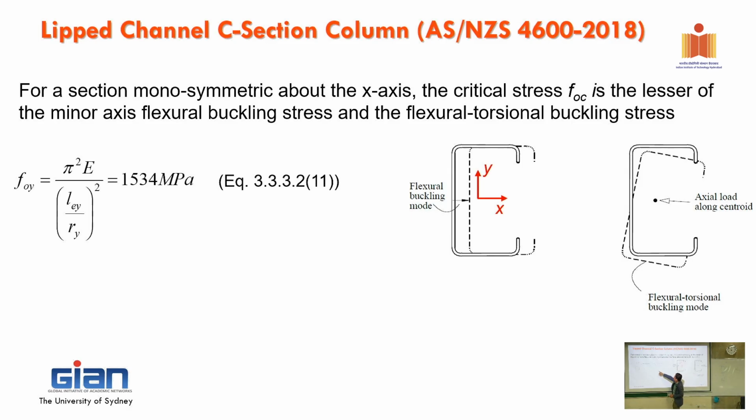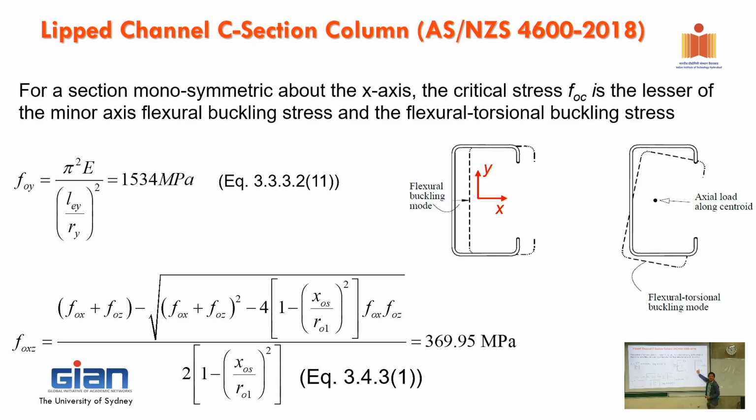The one where I break the rules, then it buckles in this one. Then it's happening here. That is Fey. That's the buckling stress that's going to happen. However, this is when it's long. But when it's getting shorter, and somehow you've got this guy to help, so you're pushing up the buckling stress of Fey, it is bigger. Then it's not going to buckle in this one. But then it starts to twist and buckle sideways in the x-axis. Then that's what happens.